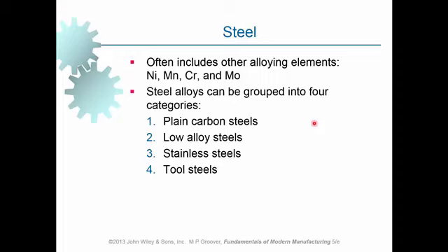And as there is more chromium, it will be more resistant, of course, to corrosion. And this is something that we'll discuss in advanced materials and manufacturing more. So presence of a lot of chromium will help form an adhesive layer on the surface of the stainless steel, protecting it in corrosive environments. And in many cases, stainless steels are also strong. Reason? Because of carbon content indeed. Carbon content will also increase its strength. Indeed, as there is higher carbon content in the material, it becomes more and more strong.